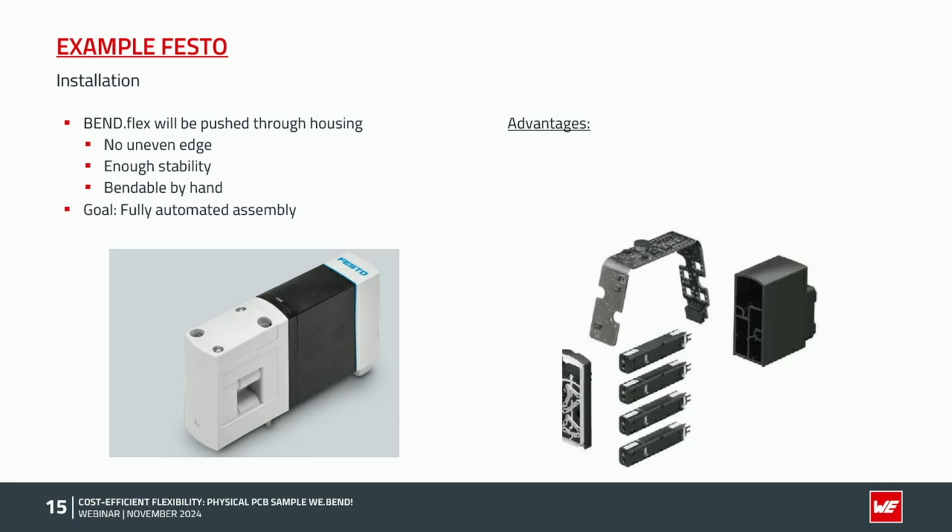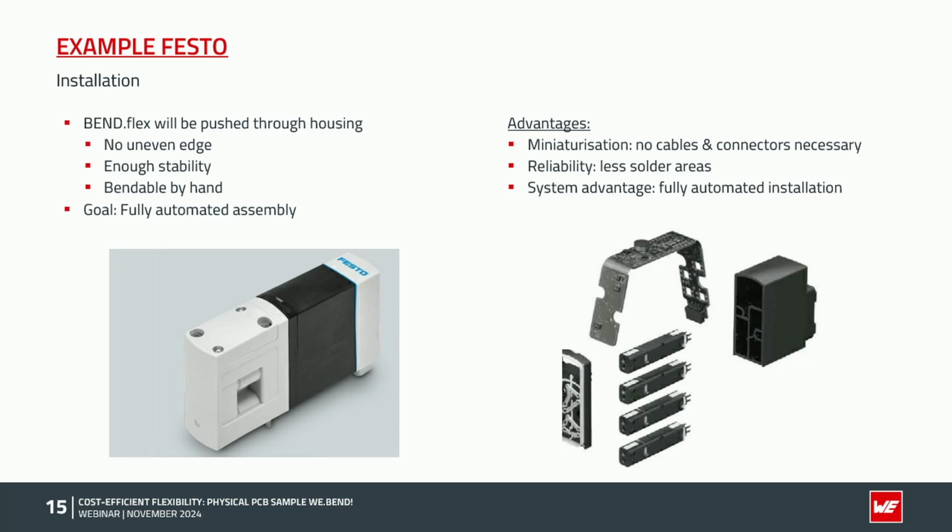The big advantages here have been the miniaturization, because we have no cables, no connectors, and we have microvias from layer 1 to layer 3. The reliability is a lot higher because we have fewer solder areas and only one system. And of course we have a system advantage, because the customer can install the PCB fully automated.